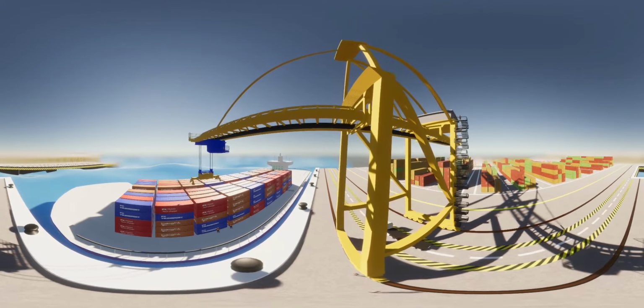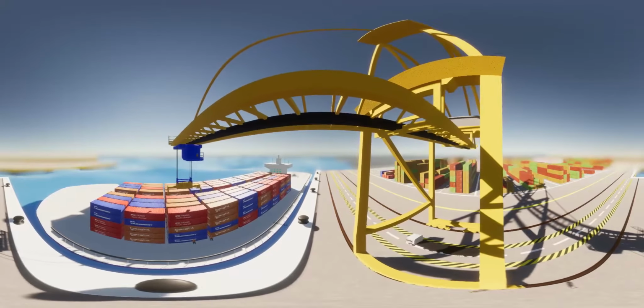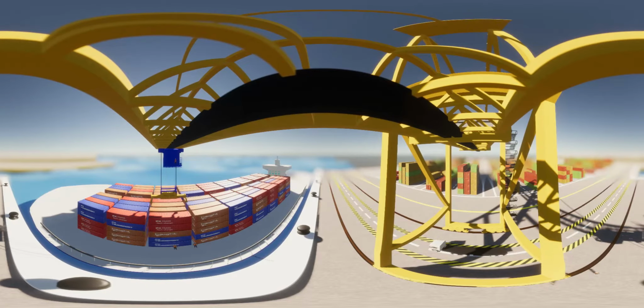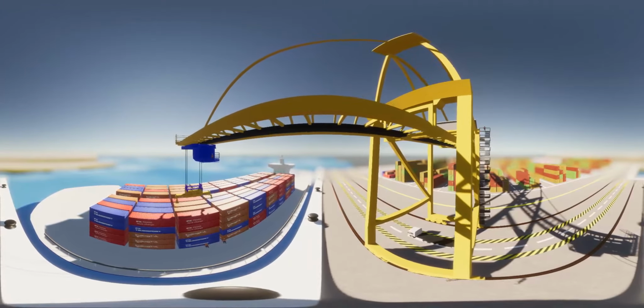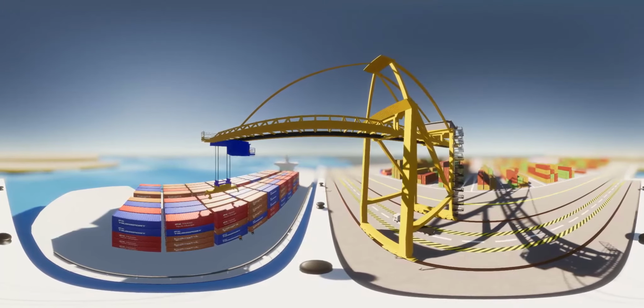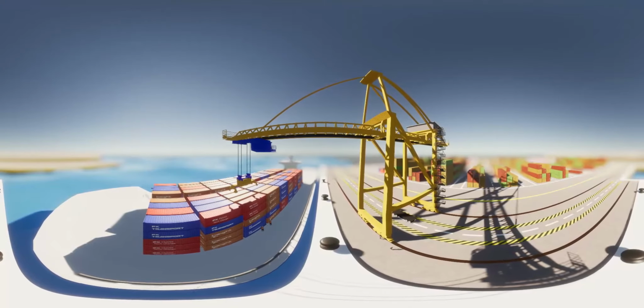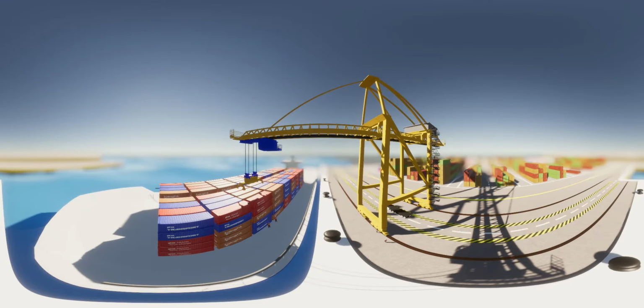Ensure that there are no obstacles on the trolley rails before trolley travel. If any abnormal noise is heard during trolley travel, stop and inform control. So in final, don't travel the trolley too fast, and also not in a defective condition.